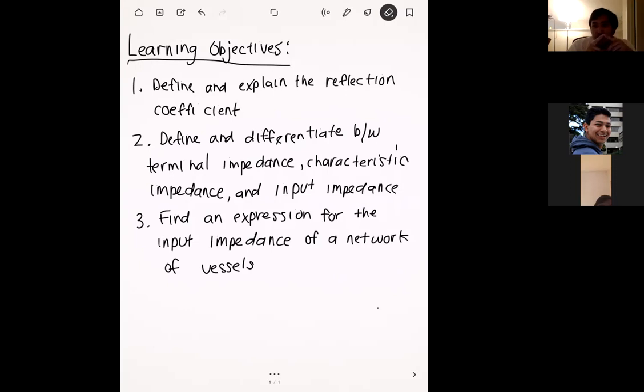Generally, what you're looking for in mesh quality is how distorted your elements are, which can be really hard to judge because sometimes you might have a really distorted element on the interior of your mesh, and it's impossible to see because it's on the inside. There are programs where you can test mesh quality.